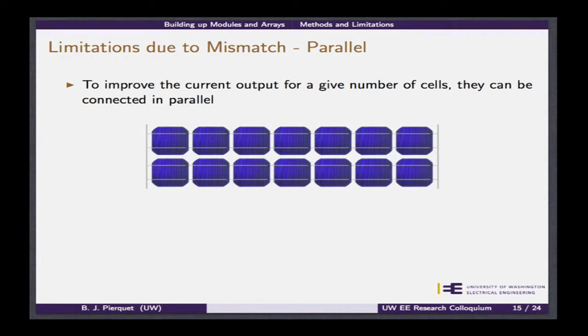So what ends up happening is you put a little diode out here, so current can only flow out. But that diode's going to introduce loss. And so certainly you don't want to have too many diodes, because that's going to cause you additional losses and additional components. But if you don't have enough, then you're stuck with strings that may have issues.